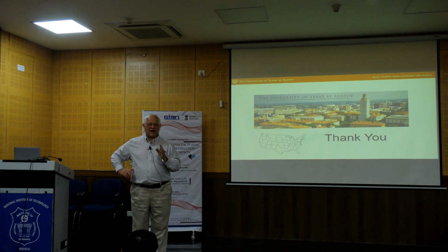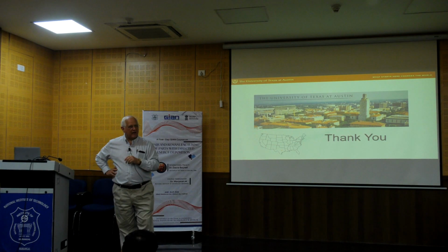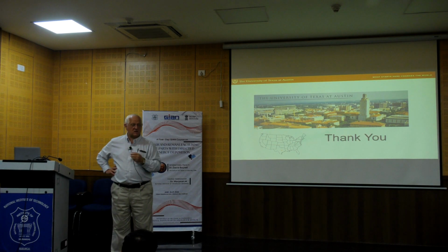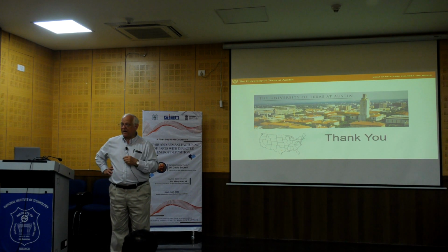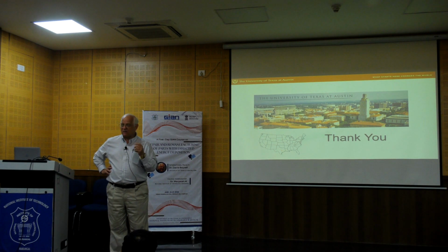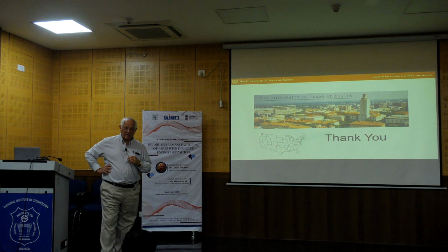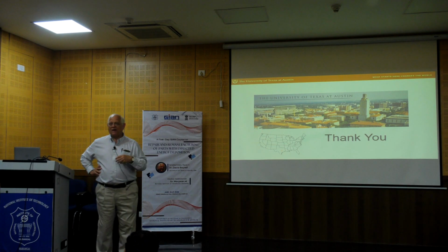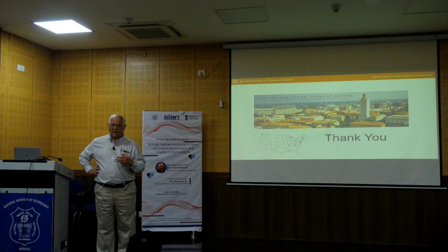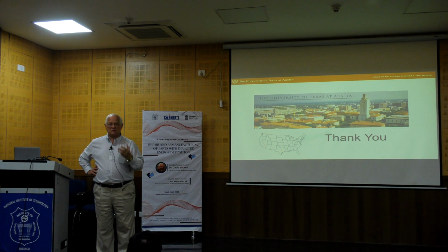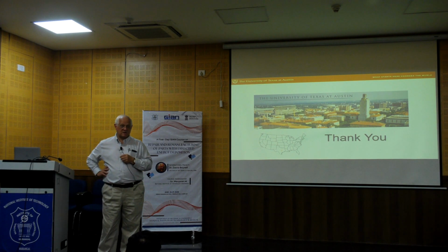And what we were chatting about was a brand new additive manufacturing machine that had just hit the market, produced by EOS. It was a polymer powder bed fusion machine specifically designed for processing PEEK powder, polyether ether ketone. It's a very popular material with a lot of applications in biomedical as well as other places. It's very hardy, but relatively difficult to process.